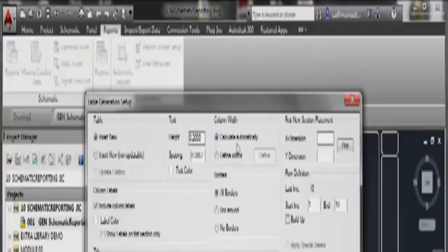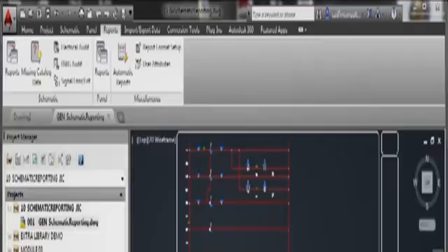I've got column widths calculate automatically, or I can define widths if I want to. I want all borders showing, and I want a first new section placement. So I can actually set this up so it always goes in the same place on every drawing I put a report into. And I've also got the row definition and the rows for each section. I don't need to worry about any of that really. I'm just going to place this manually in the drawing using the mouse in a moment. So when I click on OK now, there's my table. And what I'm going to do is just line that up by eye there and click.